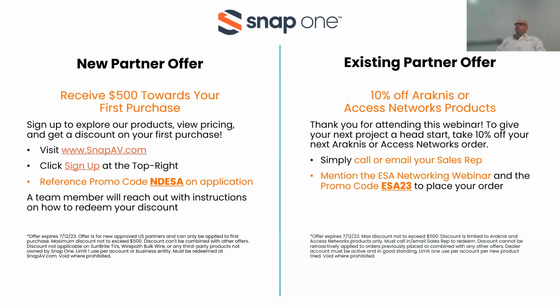And while my techs were terminating, we tested every single cable, so we knew we'd certified every cable at the time of termination, so you didn't have to climb up and down the ladders. Bing, bing, bing. Punch down, test, punch down, test.